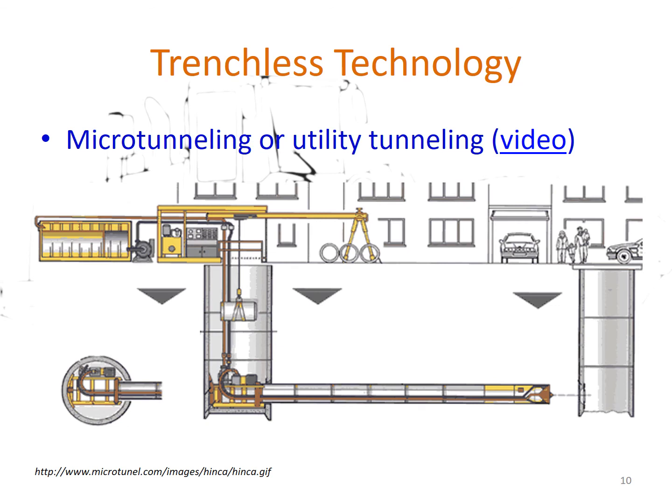And the last one is called micro tunneling or utility tunneling. I have a video here to see how it's set up. Basically, when you have a big pipe, like a main raw water pipe from the reservoir back to the water treatment plant, and you go through the river or the road, you can use micro tunneling, and we have a similar jacking shaft and receiving shaft as you have here. In this case, it can go very deep, 100 feet. Relating to the clamshell excavator we covered earlier, they can use a clamshell to excavate the dirt out, make the shaft, and then put the pipe down, one pipe by one pipe, until they go through to finish the work.